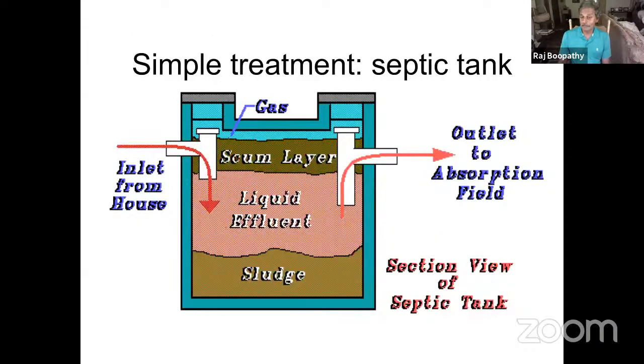And then we have a lot of rural population, and everybody has to have a septic tank or individual sewage plant. And this is highly regulated. People come and inspect your home. So you need to make sure you're doing it really well, and you have to put a chlorine tablet in every week, so make sure your pathogens are not getting out. So this is for a system that is in a rural area.